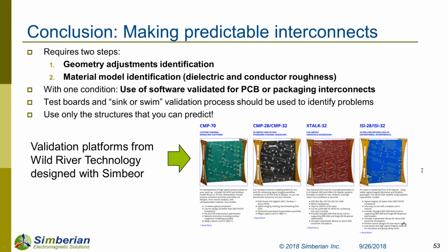You'll be surprised, but I have to answer your question about what the parameters were for the conductor surface roughness characterization. SR and RF abbreviations. It comes from the unified model where there are two parameters. The first parameter is SR, surface roughness, in micrometers. It approximately correlates with the RA or SA measurement for the conductor surface. So it's a kind of mechanical peak to valley. It's not exactly, but it correlates. You can use it and fix it as root mean square or peak to valley.